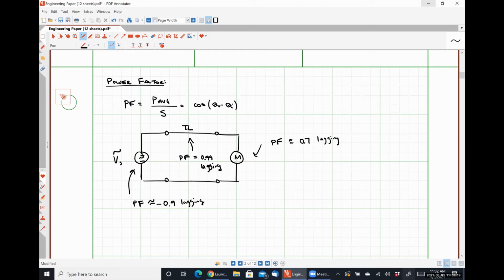All right. So when a load is operating at a power factor of less than 1 in magnitude, it means that the source is being required to generate more than the minimum volt amperes necessary to supply the required average power needs of the load. Okay, so if the power factor is 1, that means that the average power and the apparent power are identical. You're operating at 100% efficiency. If the power factor is less than 1, then that means you have introduced some inefficiency to the network, which means the network has to supply some reactive power as well to meet with the demands.